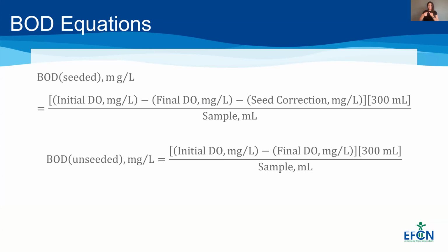So the first one is the actual BOD analysis equations that we have. A lot of times this is how our lab analysts will utilize BOD. So just calculating those BOD 5 tests, this is typically how the BOD concentration is calculated. You may have a seeded test, which is used for quality assurance, or the BOD unseeded, which is just a raw measurement of how much BOD is being consumed by the wastewater, and a raw measurement of what the organic strength of your wastewater samples is.